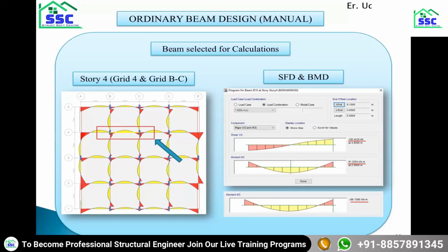When I say an ordinary beam or an ordinary column, it means that I am designing my structure for pure gravity load. So you can represent it to the small structures that we design, say some small bungalow or a small row house where we don't want to consider earthquake loads. So that beam we represent here in the workshop as an ordinary beam.